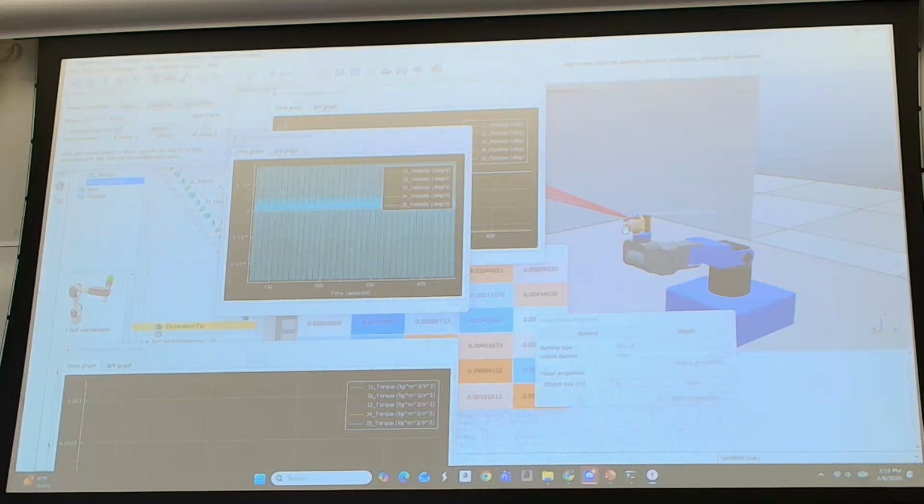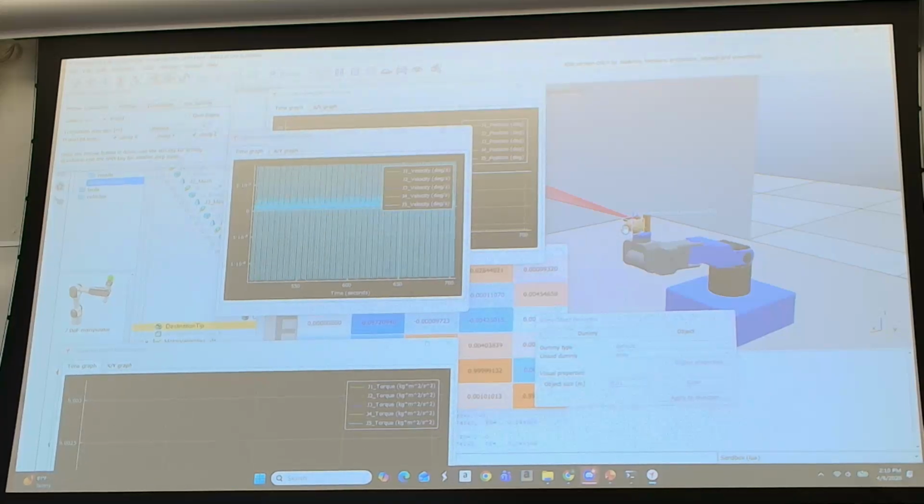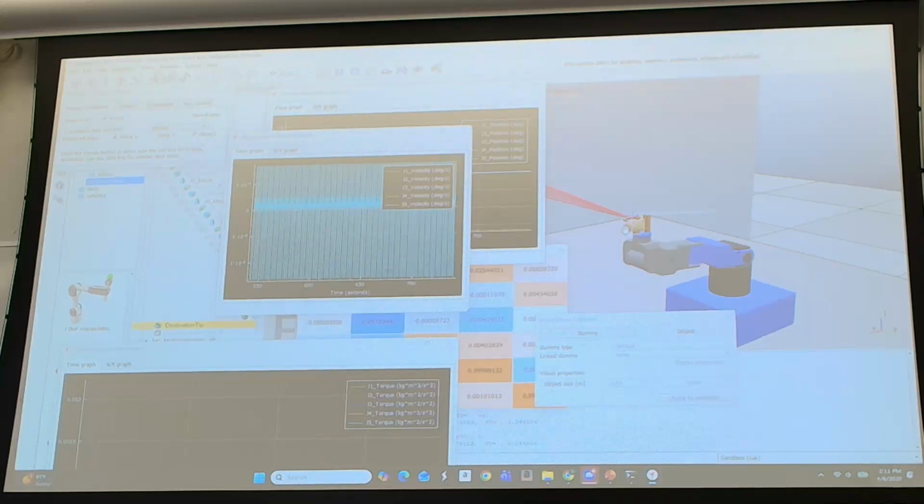Oh, yeah. So in other words, I'm asking for 10 amps because I want to go that fast because it takes that much torque, but I can only give 5 amps. Which means I'm trying to accelerate too fast, or I have too much load, or a combination of the two. So I have to be very careful how much force I have before I figure out how fast I can accelerate. All right? That's what we talk about in Lagrange.